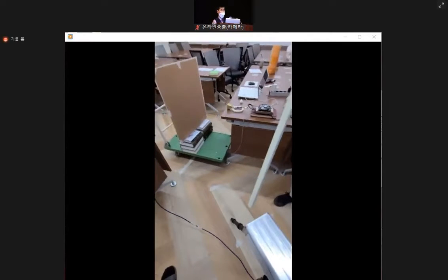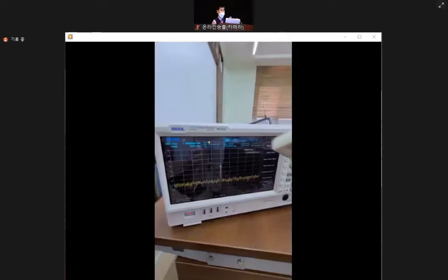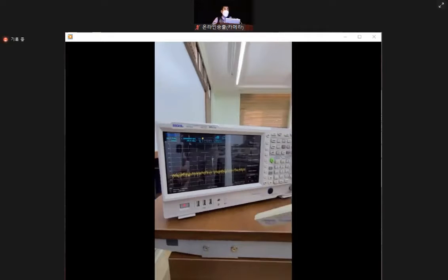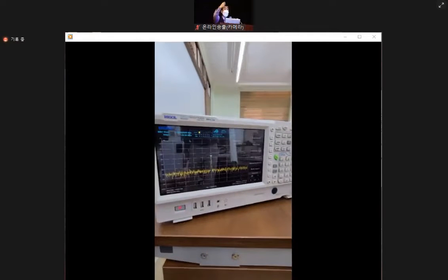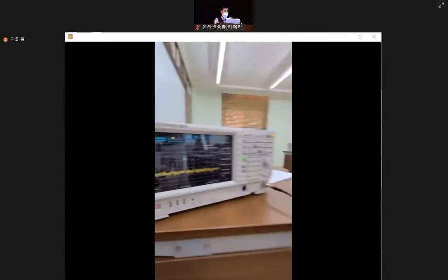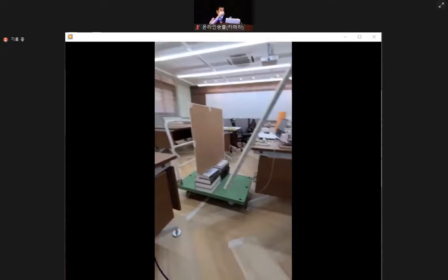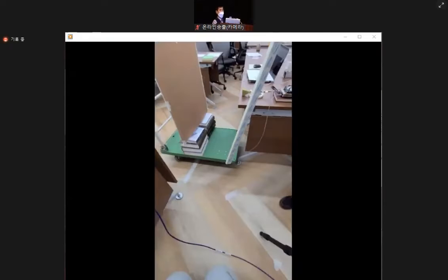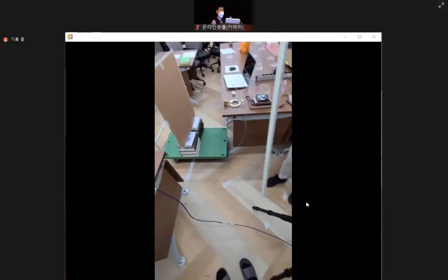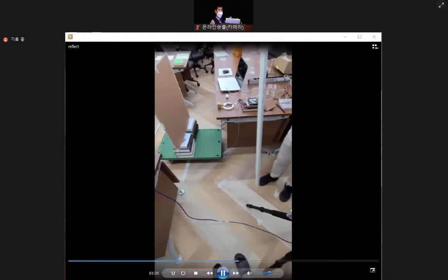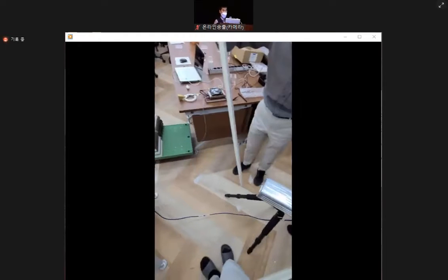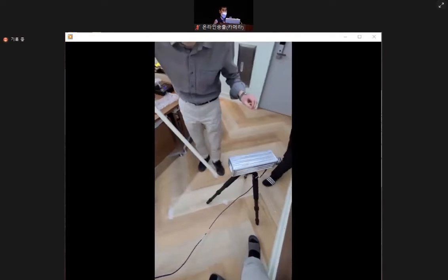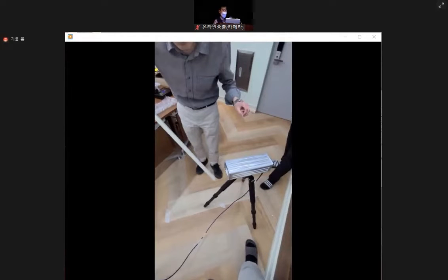Here we will read the strength. This spectrum analyzer is attached through the cable to the probe. Some dBm. You can see the green marker there that tells you the strength. The signal strength is lower than before. Why? At the same angular position, but the distance has increased. So it is no wonder we can see the weakening of the received power strength.